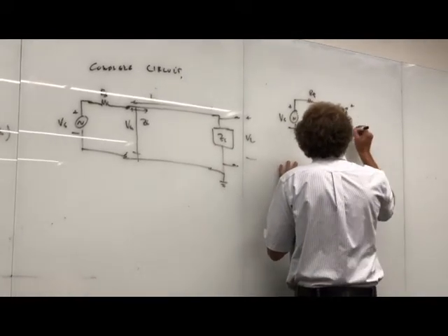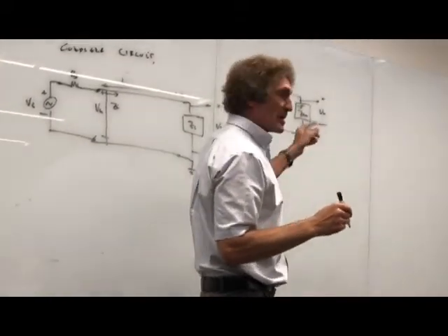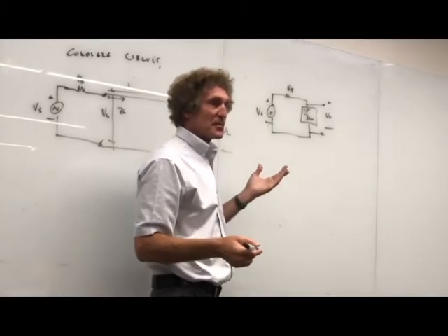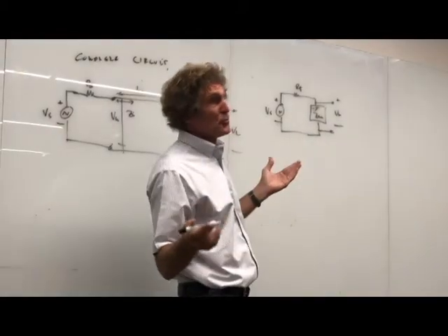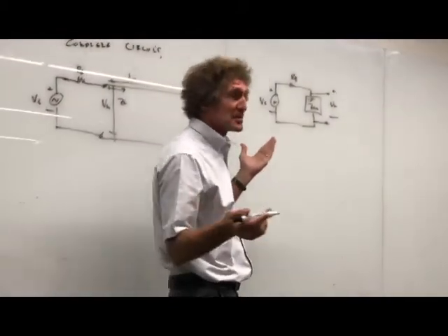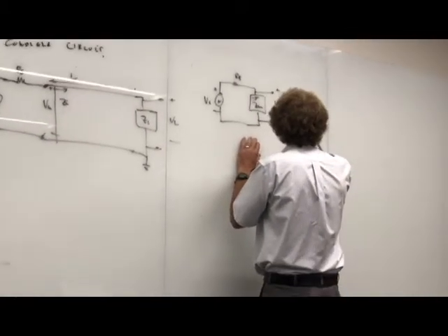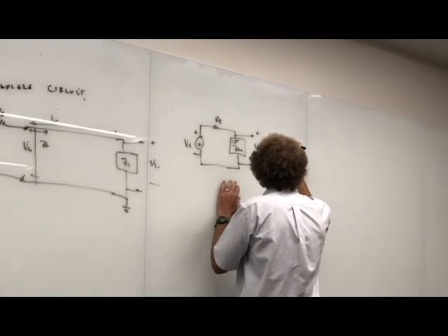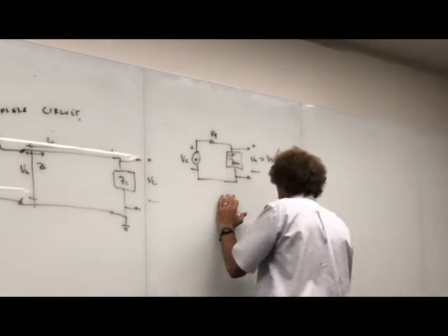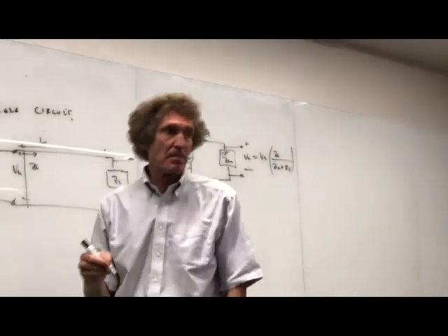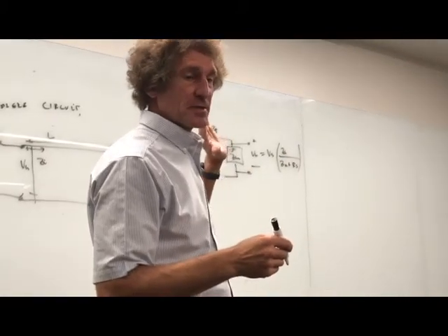And what I want is this voltage here. I want to get plus to minus Vn. With me? Vn right there, how would you get it? Just think about it. What is Vn? Voltage divider. That's it. I got two impedances in series and a source voltage, right? That means this input voltage is simply Vs times Zn over Zn plus R source. Do you agree with me?